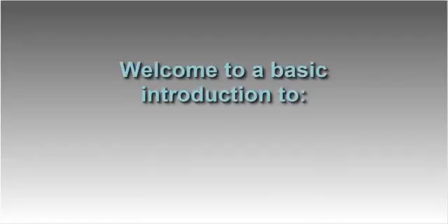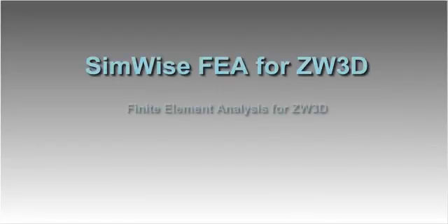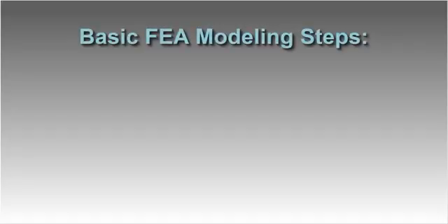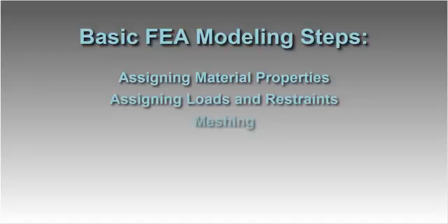Hello, and welcome to a basic video introduction to SimWise FEA for ZW3D, Finite Element Analysis for ZW3D. In this video demonstration, we'll look at the basic steps involved in setting up and analyzing an FEA. That involves assigning proper material properties, proper loads and restraints, meshing the model, and then finally post-processing the results.